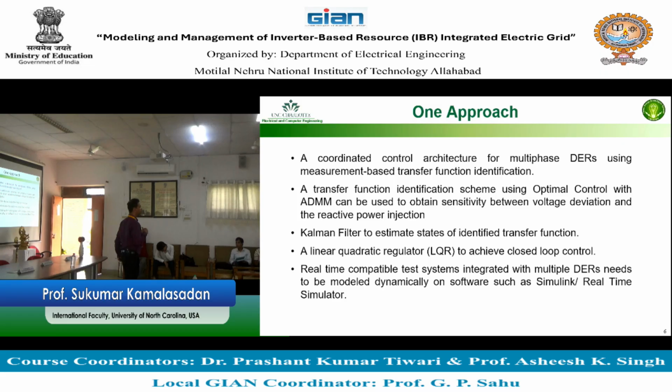If you are running an optimal power flow or a power flow, you are going to do either tertiary control or secondary control. You don't do device level control, which means that the signal of the power comes to the substation, saying, hey, I need this signal. That signal goes to the group of DERs and says, I need this from you, this from you, this from you. Then this goes to each DER and says, I need your contribution. So you divide them up, that's how you send a signal. When we are talking here, we are talking about sending the signal to individual DERs for reactive power compensation.